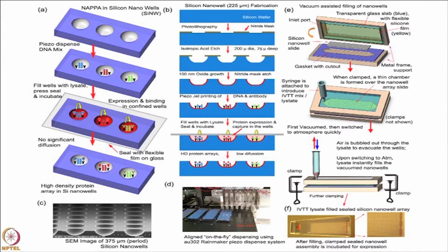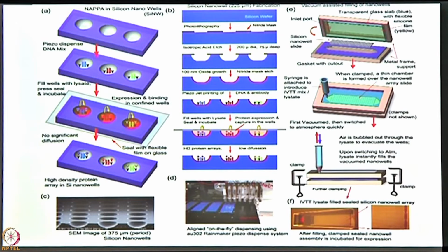What we do is we take silicon, the same material that you use to make computer chips, and we use the same technical approach that they use, what's called photolithography, whereby shining light on the surface you create a mask, and then you etch it with chemical compounds that etch away the surface, and you essentially can wear away the surface of the silicon. And what we do is we create these little, what we call nanowells. Nano because they're nanometers in size. In fact, in terms of fluid volume, they hold picoliters of liquid, so they're very, very small. And so we etch away those wells.